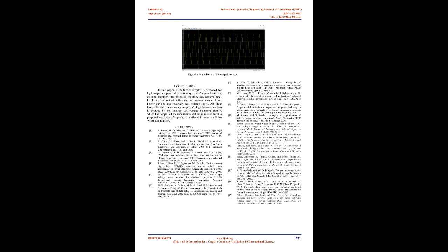The main advantage of pulse width modulation, PWM, control strategies is to reduce the total harmonic distortion, THD, of the output voltage. The switching frequency of the inverter is the frequency of the carrier signal. Multiple carriers PWM techniques are always used in multilevel applications. 3.1 Functioning of the proposed model.